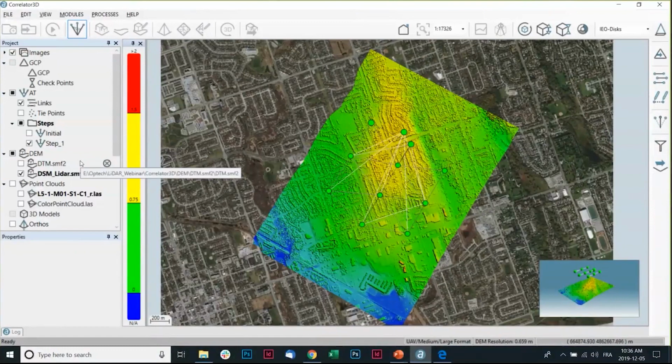As I mentioned before, the advantage of using the LiDAR for ortho rectification is that LiDAR is usually much better suited for true ortho generation, because you have much cleaner edges on your buildings. When you try to calculate the displacement of every pixel, such as buildings and everything, you really need a really sharp DSM to do true ortho generation.